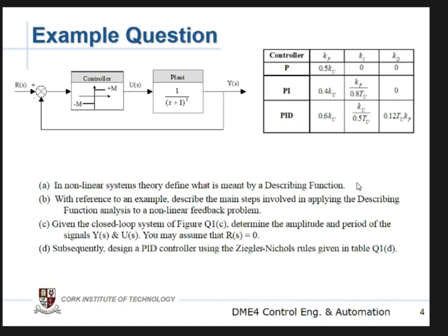In order to establish that, we're thinking of our Bode plots, for example, and a low pass characteristic. If we look at the amplitude part of that, we'd expect the gain, if it started at 0 dBs, as we go up in frequency, to start doing something like this. So the gain of the system reduces or attenuates as we go up in frequency. The argument for this is that the low pass characteristic cuts off any high frequency elements that are generated by our nonlinearity.